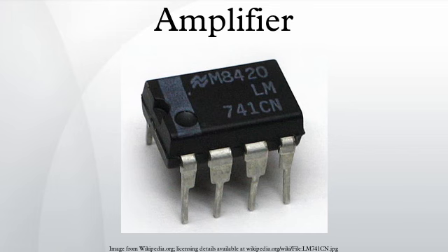Figures of merit. Amplifier quality is characterized by a list of specifications that includes gain, the ratio between the magnitude of output and input signals; bandwidth, the width of the useful frequency range; efficiency, the ratio between the power of the output and total power consumption; linearity, the degree of proportionality between input and output; noise, a measure of undesired noise mixed into the output; output dynamic range, the ratio of the largest and the smallest useful output levels; slew rate, the maximum rate of change of the output; rise time, settling time, ringing and overshoot that characterize the step response; stability, the ability to avoid self-oscillation.